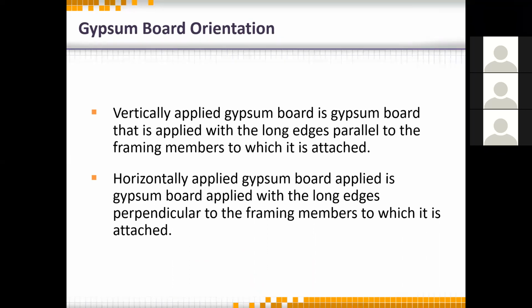Horizontally is obviously laid over on its side. We do that a lot in residential construction. We sell a 54-inch wide board with 2 layers of that. You get a 9-foot ceiling, and that's perfectly fine. But if a UL test was done vertically, and that's it, that's the way it was installed, contractor has to install it vertically. They cannot on their own lay it on its side and go horizontal.